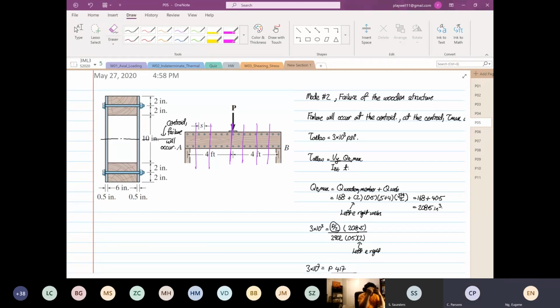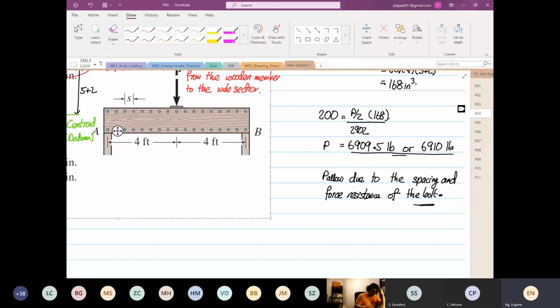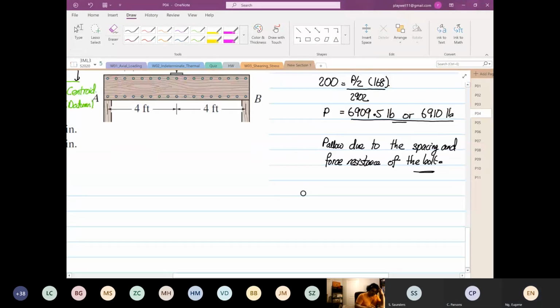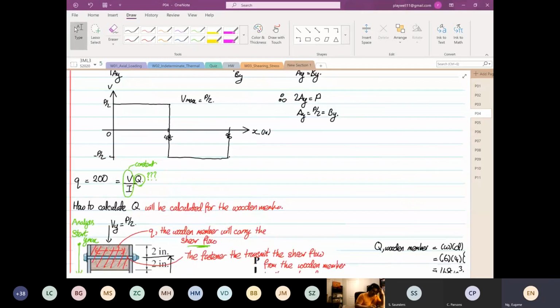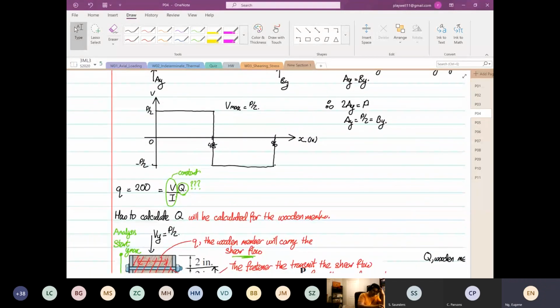You're partly right. This is because if you look at the shear force distribution, right? V max is equal to P over 2. So V max can be anywhere. It can be here, it can fail here, it can be here. So that is the reason. For just shear alone. If we include bending moment, it's definitely going to be in the center. Okay?